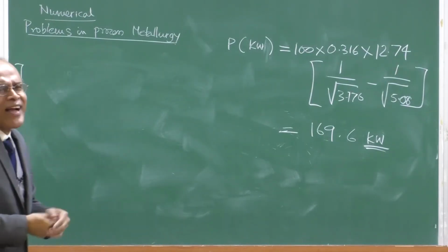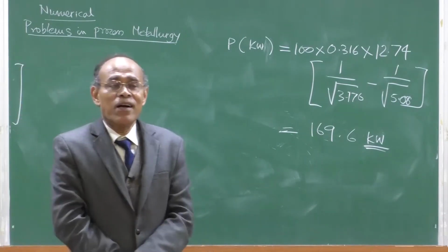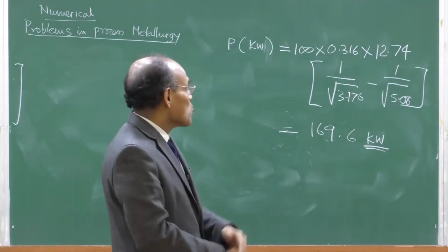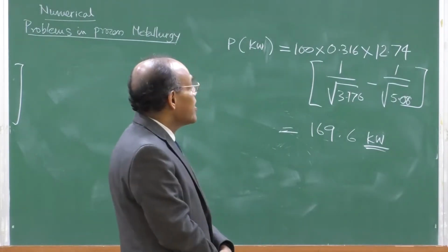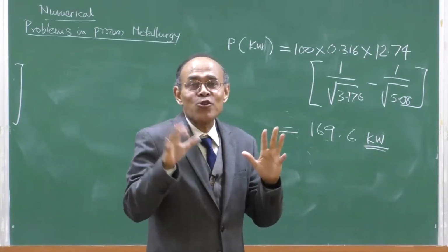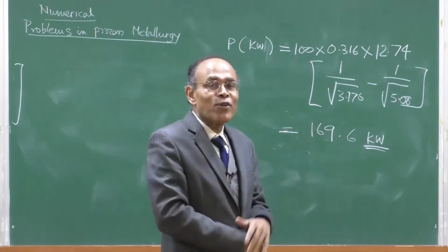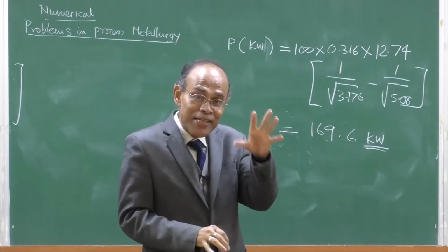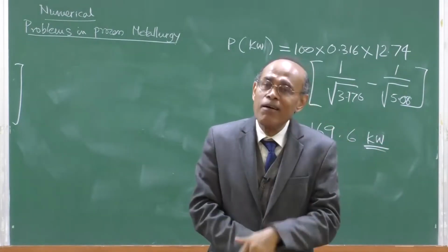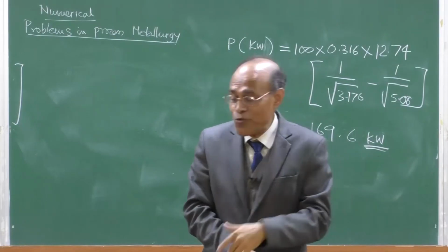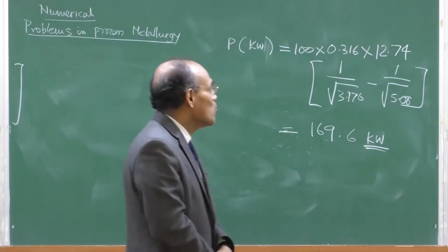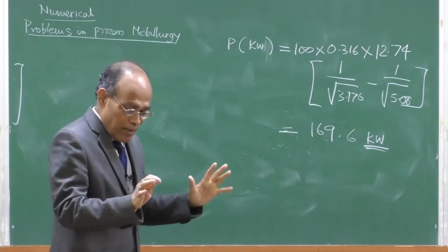So, this is typically the kind of problem that you can expect either in an exam like GATE or in your classroom examination from mineral engineering, and these are very simple, there is no reason why you should mug it up, it should come out very spontaneously. One or two pulp density issues, and similarly the particle size in the Bond's equation as in millimeter, not in inch or other units. These are the few things which you have to remember and just plug in the values and you should be able to calculate.